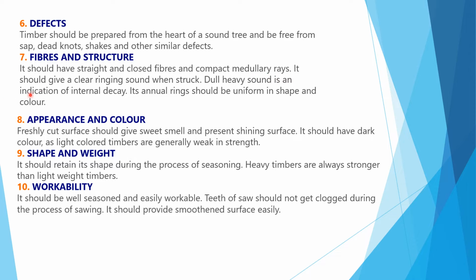Medullary rays. It should give a clear ringing sound. A dull, heavy sound when struck is an indication of internal decay. Its annual rings should be uniform in shape and color.